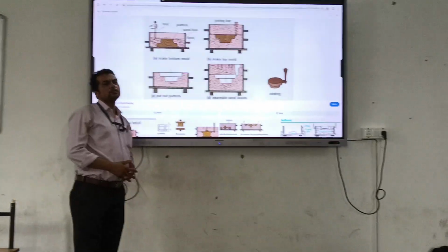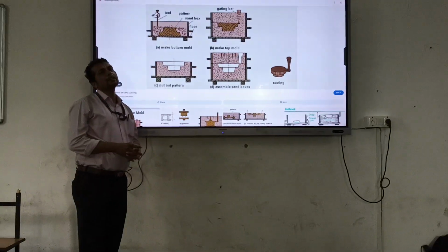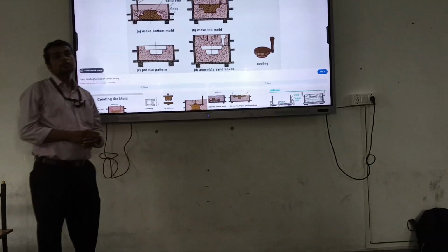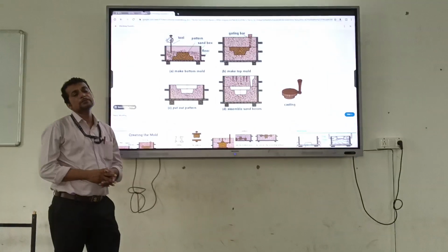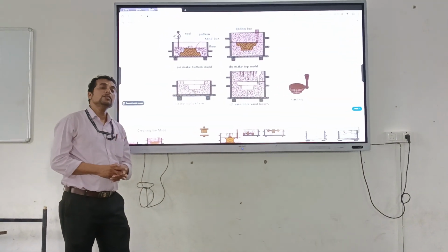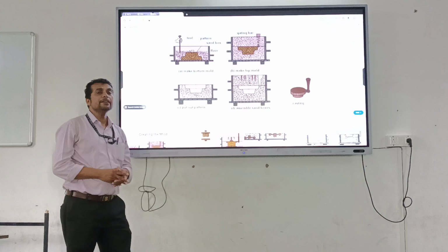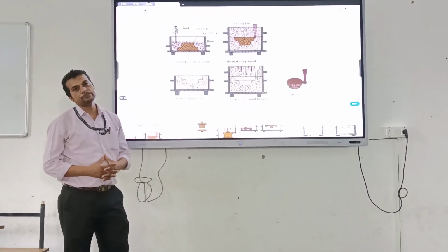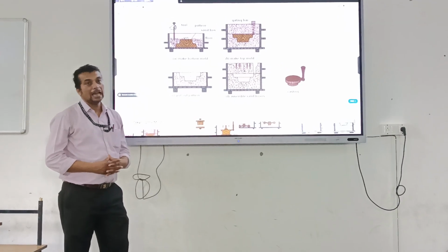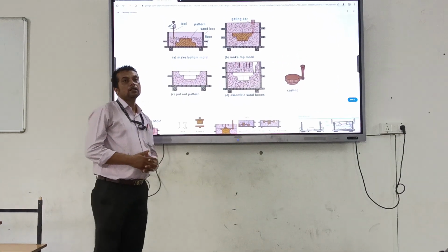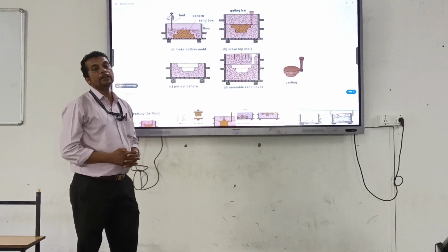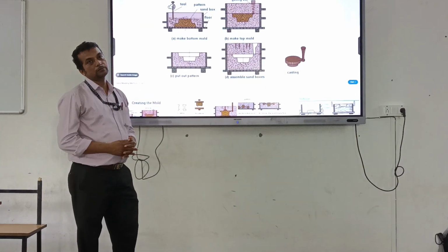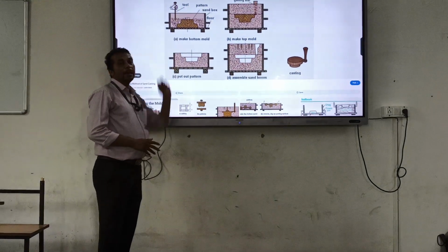Why do we need very fine sand? The question arises in our mind. Because by using fine sand, we can get a very fine quality of mold cavity. That's the need. We use fine sand over the master pattern.